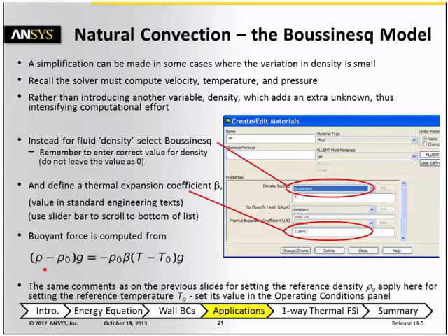What happens in Fluent after you do this is that the buoyancy term in the momentum equation, which you see on the left-hand side of the equal sign here, is replaced with an equivalent expression on the right-hand side of the equal sign, where instead of density difference, the buoyancy is proportional to the temperature difference. So this only works when density variations are small.